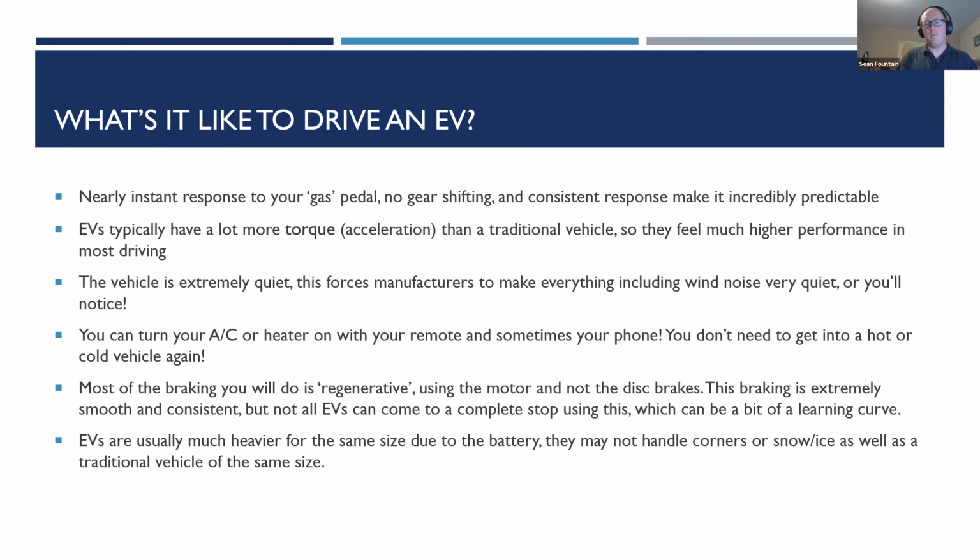So in a gas engine vehicle, brakes don't work as well if the engine is off. And that's because the engine has a vacuum, a big giant drum, essentially a diaphragm, and when it's sucking air in, it's applying vacuum to that drum. And when you press the brake pedal, it acts like a big amplifier and makes your brake pedal press that much harder to the hydraulics in the brake system. And that's why they say pump the brakes if you don't have ABS. Well, the same holds true if your engine is shut off, you can pump the brakes and build brake pressure. Same with electric vehicles.